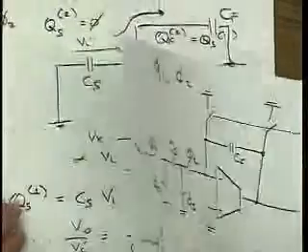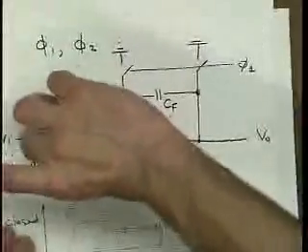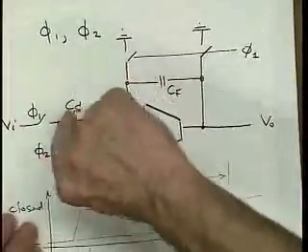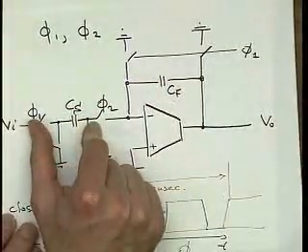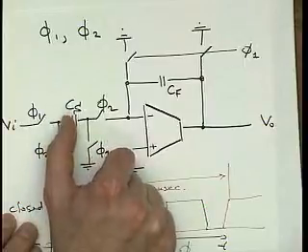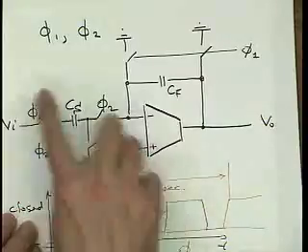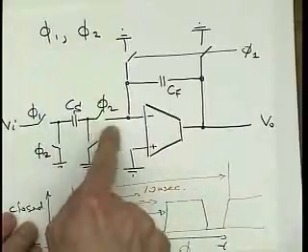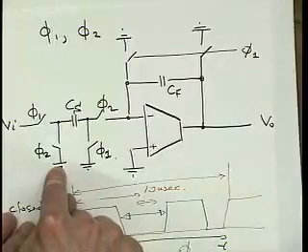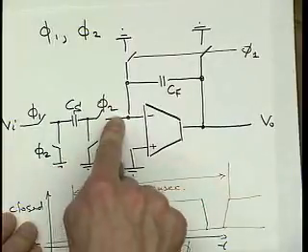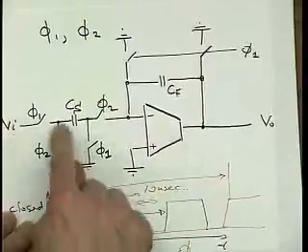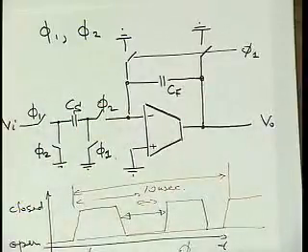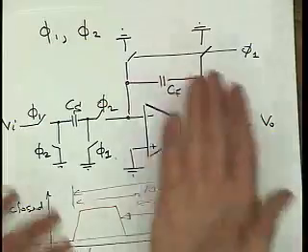Because what happens is that we are charging this Cs to the input voltage like this, and then we flip around using the switch arrangement. We flip effectively around the capacitor so that now suddenly the other side is grounded and no longer connected to the input. The input now effectively has gone to the other side. So that produces an inversion here, and then the amplifier produces another inversion altogether. It's a positive amplification. So actually that's a very nice side effect of using this switch business.